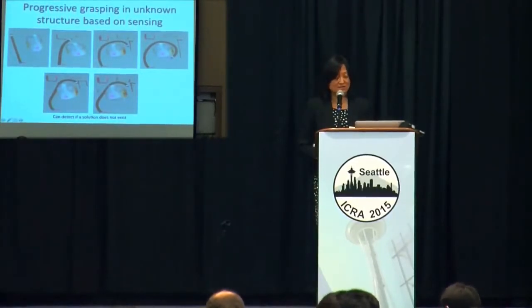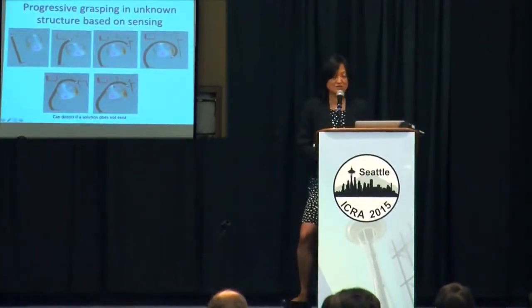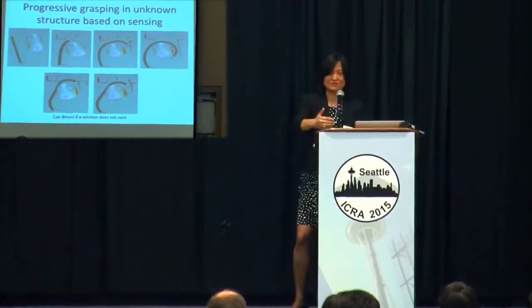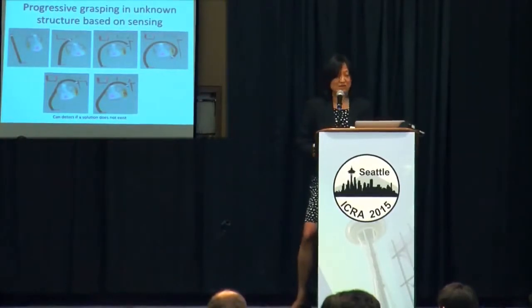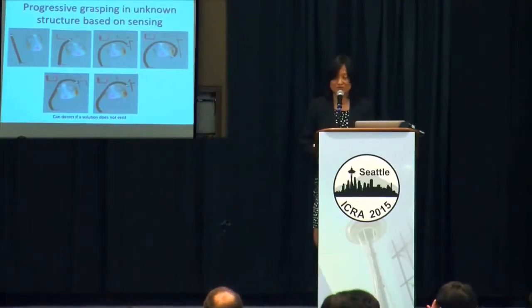And in this case, the gap is wide enough for the same area to be grasped, but in order to make this robot wrap around this object, the top space is too narrow. So we have to consider a concatenation of these so-called gap constraints simultaneously as we start discovering the structure and object, to decide if a solution exists. If a solution exists, we can always find it.